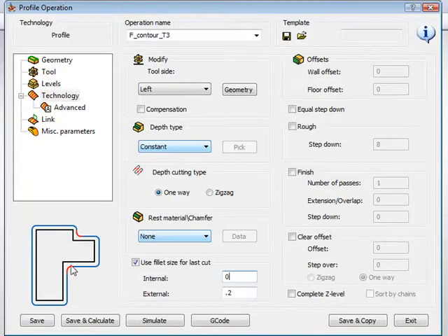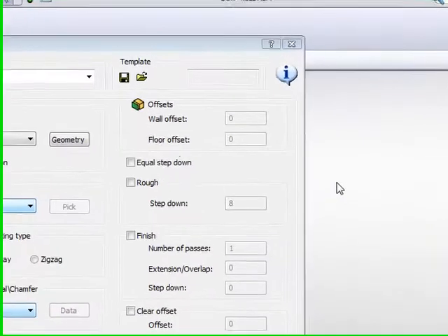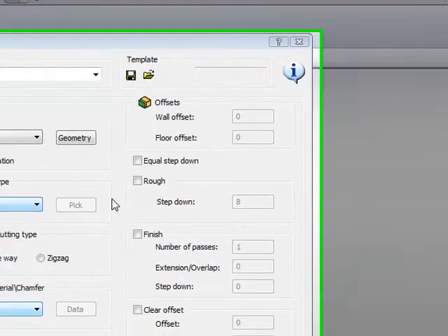If my tool radius is the same size as my radius over here, or larger, especially when you have a sharp corner, so every tool is larger, it'll create the center tool path with a slight radius, thereby not putting extra pressure on this wall over here. So I can put, if I need, say 0.2 millimeters as well. We'll now move over to our right hand side of our screen.